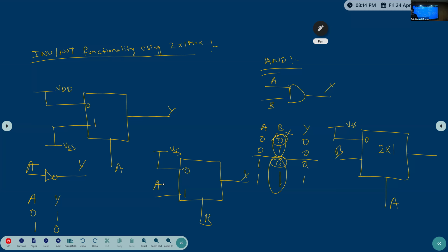Simple. Few things are there where people will be trapped. Like multiplier circuit and mux: the multiplier they will confuse first. Second thing, in the multiplier, for binary addition they will think it is logical addition. This is the second trap. And third one is this implementation: the inverter they can implement, but coming to AND gates and OR gates, they will feel a little difficulty.